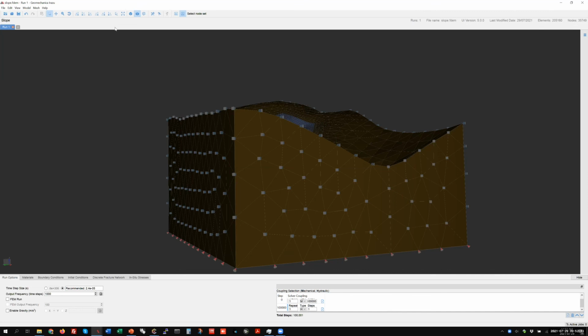Okay, and then the second part of that question, I'll go ahead and answer, which is about, if you had a code that did MPI parallelization, the kind of domain partitioning in Cubit for a mesh like that, you typically wouldn't have Cubit worry about the MPI parallelization. Usually codes that support MPI parallelization will handle node renumbering and the dynamic partitioning themselves. So that's not really something that you typically would use Cubit for, and we don't support that natively. You might be able to hack something together in Cubit to do that for your code if you wanted to, but that's something that we just typically let the solvers handle.